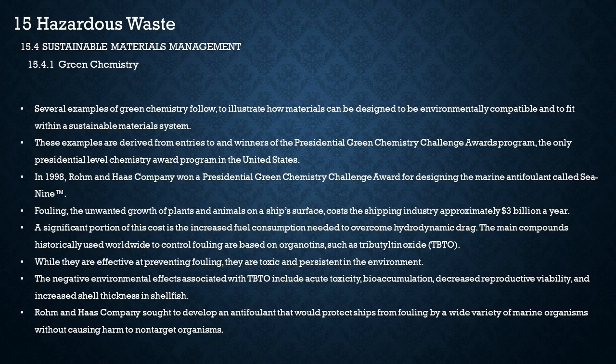Fouling, the unwanted growth of plants and animals on a ship's surface, costs the shipping industry approximately $3 billion a year. A significant portion of this cost is the increased fuel consumption needed to overcome hydrodynamic drag. The main compounds historically used worldwide to control fouling are based on organotins, such as tributyltin oxide (TBTO). While they are effective at preventing fouling, they are toxic and persistent in the environment. The negative environmental effects associated with TBTO include acute toxicity, bioaccumulation, decreased reproductive viability, and increased shell thickness in shellfish.